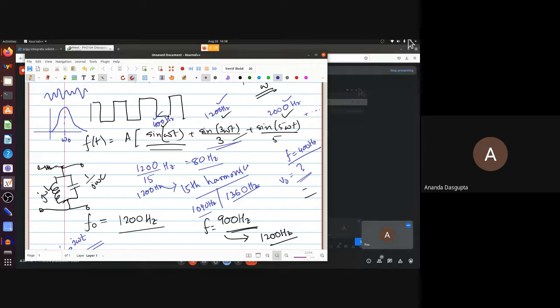That is, if I have, for example, I can easily tune the resonance frequency of this circuit by changing, say, the capacitor. If the capacitor had been a variable capacitor, I could keep on changing the resonance frequency and see where I get the resonances. I should theoretically get a resonance at 1200, then 3600, then 6000, and so on. Instead of that, what we do is we change the frequency of the input signal. Why do we do it?